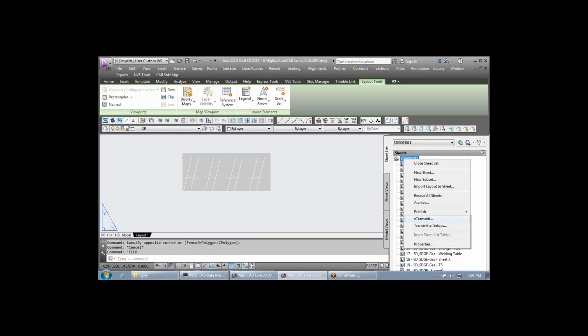Block attributes are kind of a thing of the past. They used to be very useful, but when you're inserting that block into every tab, that requires you to go to every tab unless you start doing some global attribute changes, which we can do, but there's instances where you don't necessarily want it to be totally global.